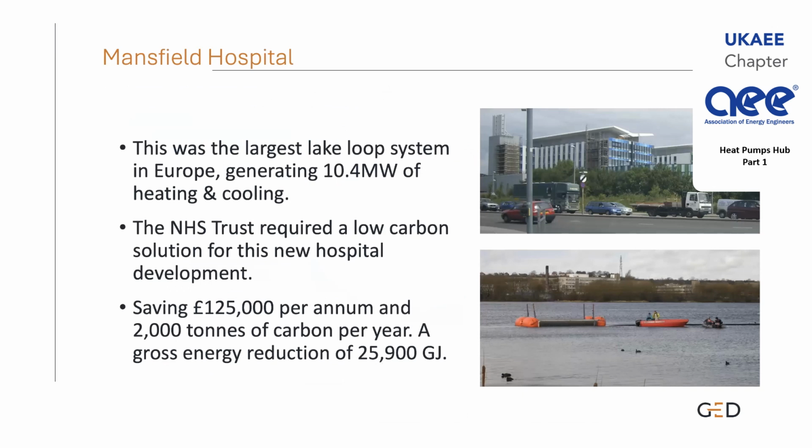Mansfield Hospital, at the time, which was in around 2012, I think, was the largest lake loop system at 10.4 megawatts of heating and cooling. The heat pumps are the sole source of cooling for that hospital. They do a huge proportion of the heating, but there is also gas boiler backup. That consisted of slim jims, as they're called, basically stainless steel radiators sunk into the lake, and we absorb energy out of that lake.